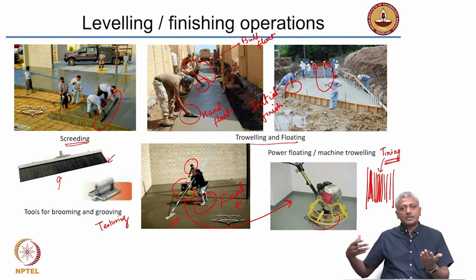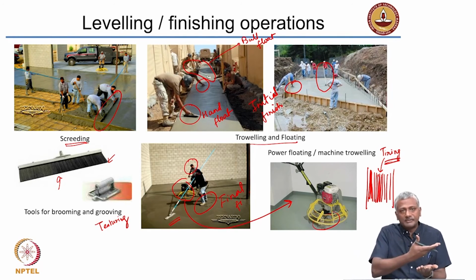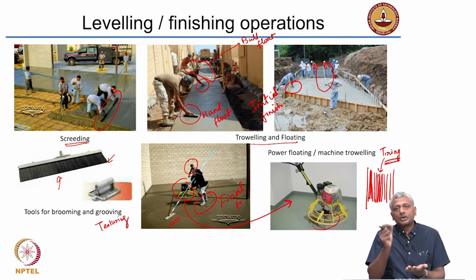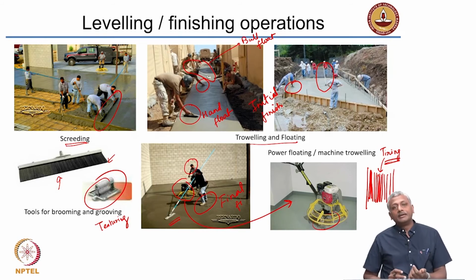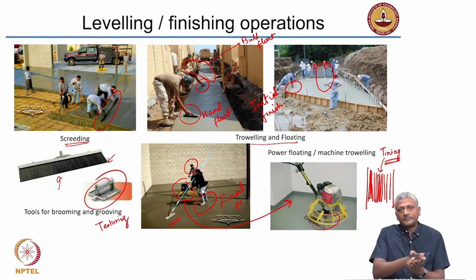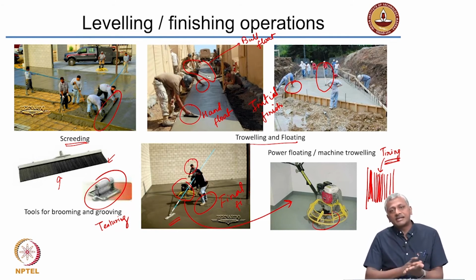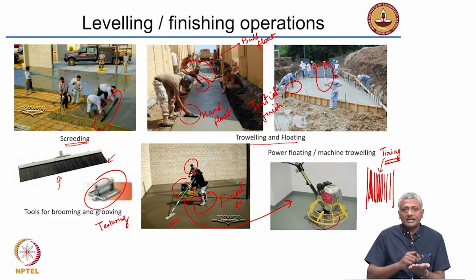And what happens is, as your vehicle passes on top of the road surface, the tining or the grooves that are provided, which are made with this sort of a grooving tool, ensure that you get the required frictional resistance, and you also get a way to reduce the amount of hydroplaning. That means when water gets in, when it is a wet condition, your vehicles can skid off. The provision of this tining or these grooves ensures that the effect of hydroplaning reduces significantly.